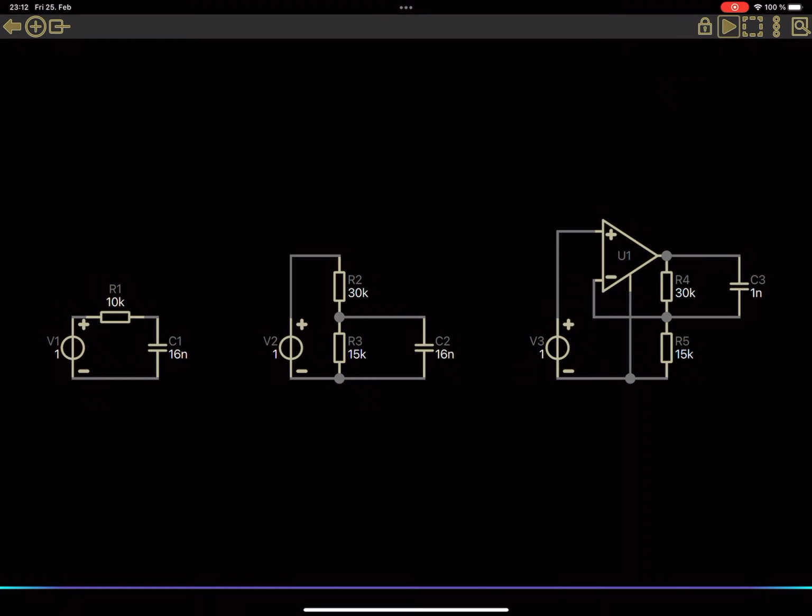In this video, we will define target values in the frequency domain. We'll show how to design basic RC low-pass filters and use this knowledge to provide our voltage divider and non-inverting operational amplifier circuit, which we have done in the previous videos, with a well-defined bandwidth limit.